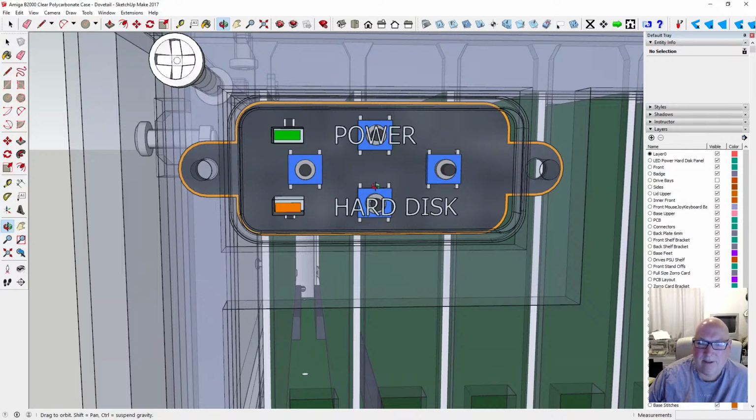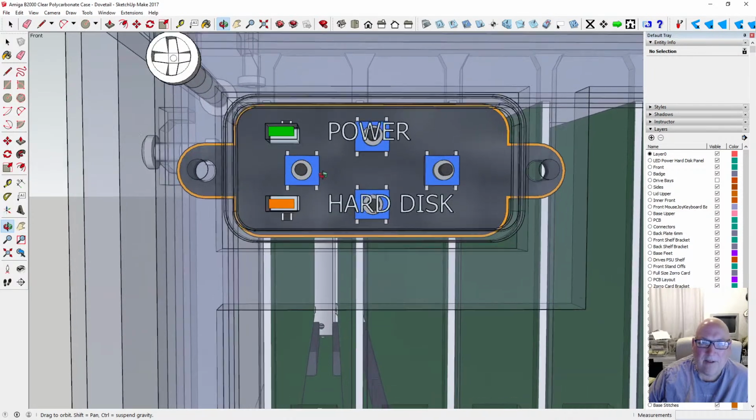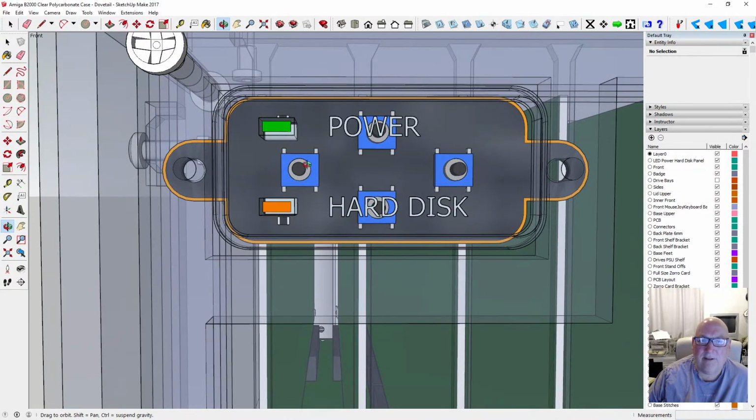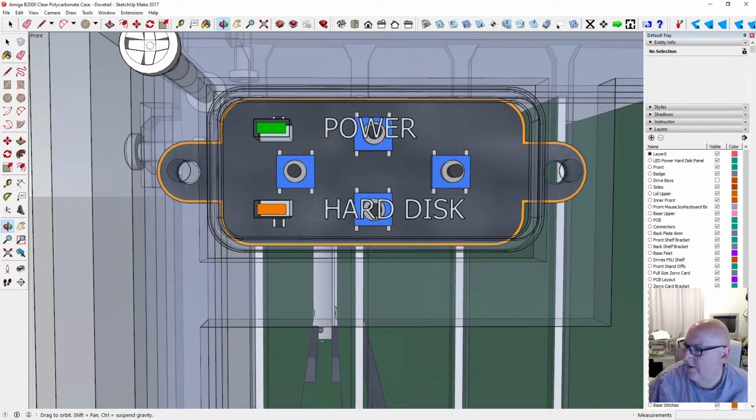I'm going to have to measure this. Normally I'd make it out of a piece of Veroboard or a breadboard, or measure the distance. Yeah, we could do that. I could get a piece of Veroboard or breadboard and push the switches in, hold the plastic up and get it in the right position. Then get this to snap to grid and stuff, but get KiCad to snap to grid.